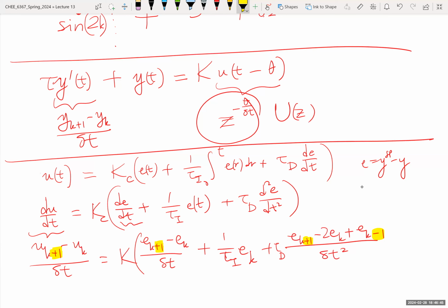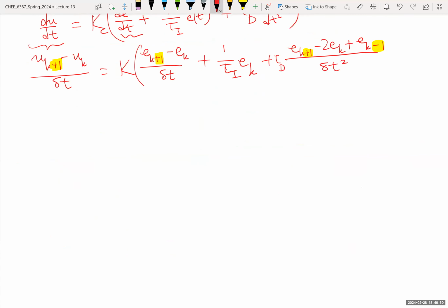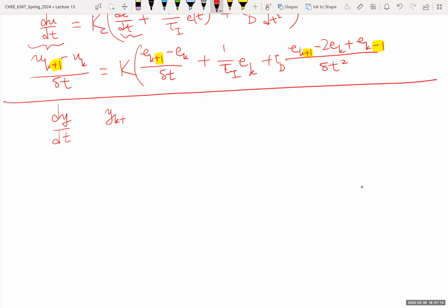Finally, before we conclude with our controller design, which we'll explore next time, and then the reverse, how you get the models that go into controller design. Section 11 says from continuous to discrete time system models, done in the transform domain. Why bother? Because if we have derivatives, and we put in place of them a difference at tk, well, this is approximate.